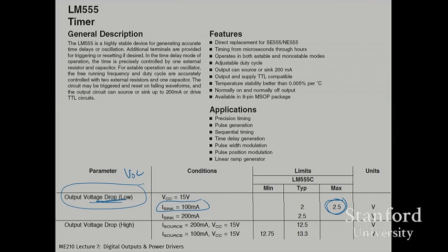That's kind of high for a driver, but if you're talking about tens to hundreds of milliamps, that's basically survivable from a power dissipation perspective. And so 555s are actually pretty nice for turning LEDs on and off and doing some other simple functionality. But it's not much current here. Remember, our logic family devices gave you up to 10 milliamps. This guy works up to maybe 100, but often we're going to need a lot more than that.